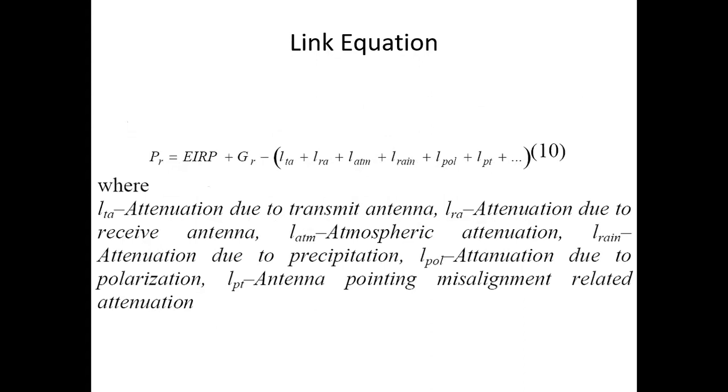So including all these components, the whole equation will be like this. You just incorporate all these types of attenuation due to polarization, if you have some polarization misalignment. So are these all in logarithmic terms? Yes, they are all in dB.